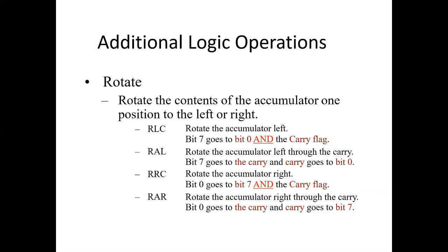Next is instruction RLC. RLC stands for rotate left accumulator. It rotates the accumulator contents to the left by 1 bit position. In this instruction, the bit that moves out from the MS bit position goes to the vacancy created in the LS bit position. Also, carry flag gets a copy of the bit moved out from the MS bit position.